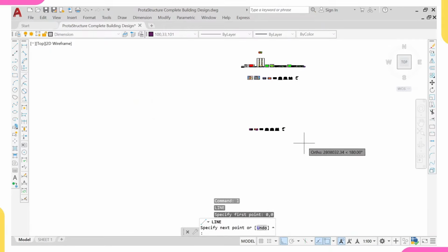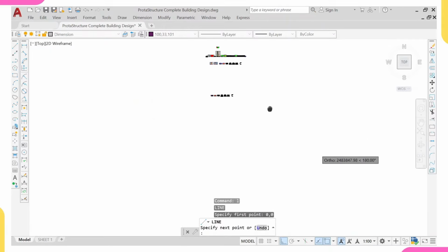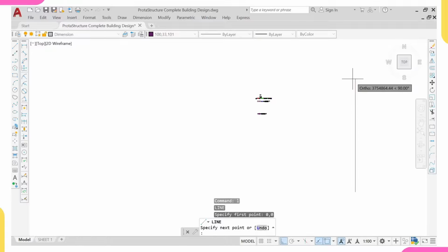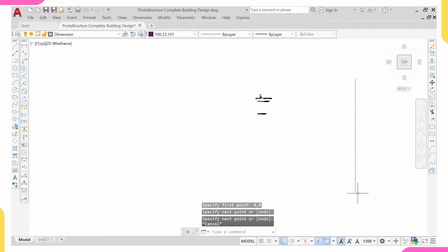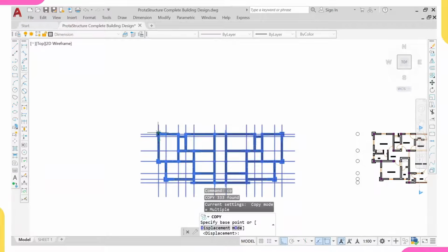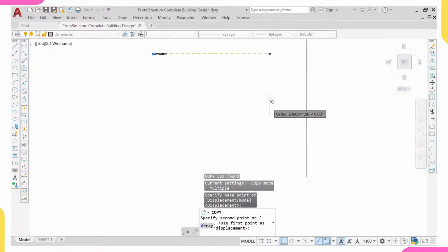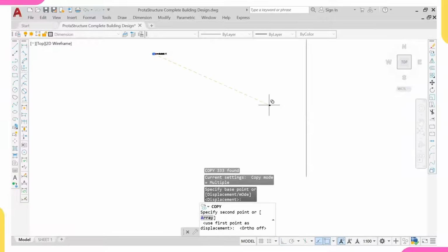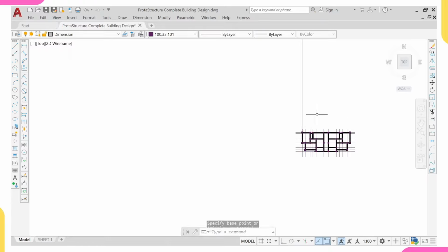So if you zoom out, wait. I have seen my origin. Look at my origin here. This is my origin. So I'll come over to this point and then do CO, enter. I'll copy this drawing from this point, remove my auto key by pressing Control F8, and locate my origin. So this is my origin. At this point I will do E, enter, delete design.